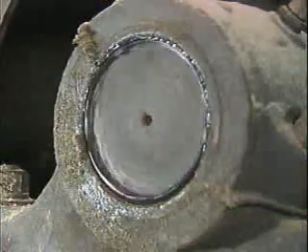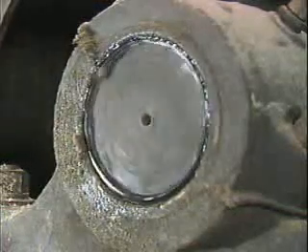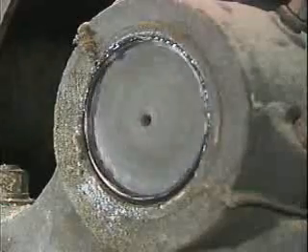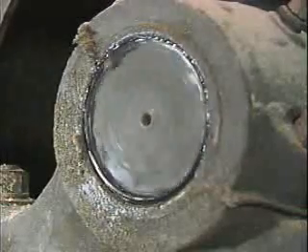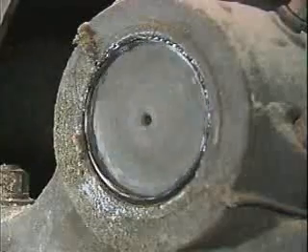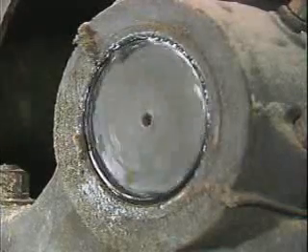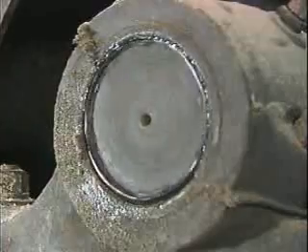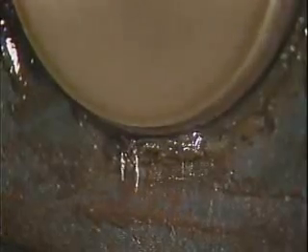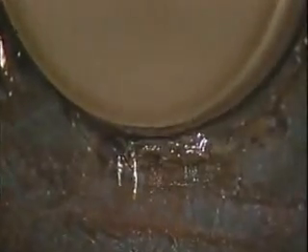Bearing applications are especially sensitive to instability. If the grease in a bearing breaks down from the heat that's generated during operation, the grease will leak out and leave the bearing dry, causing the bearing to seize. A stable grease, on the other hand, resists breaking down due to temperature increases or exposure to air, water, or reactive chemicals.